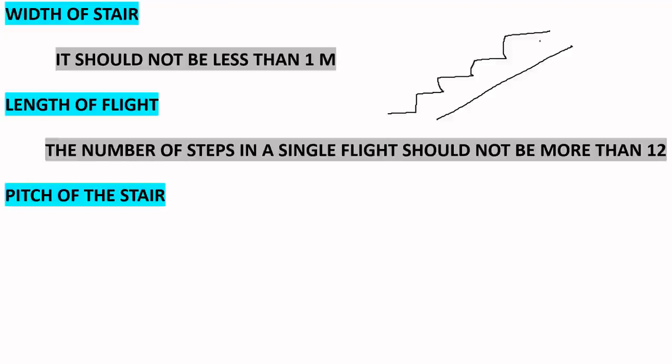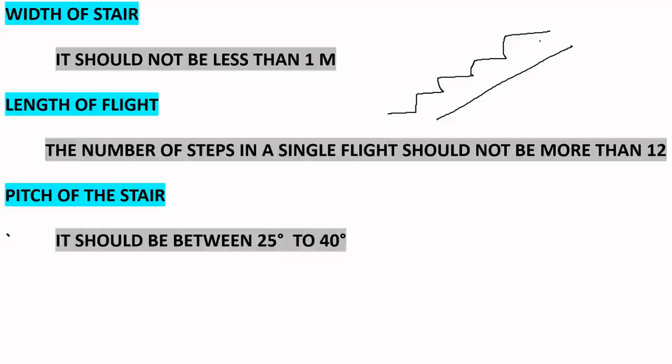Now the pitch of the stair, that is the angle between the flight and the floor, is called pitch, and this pitch should be between 25 degrees to 40 degrees, not more than that. 30 degrees will be fine.